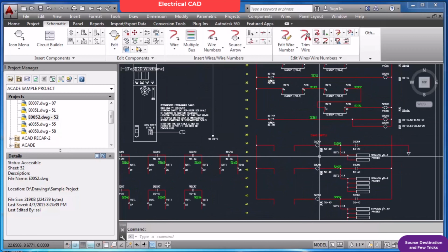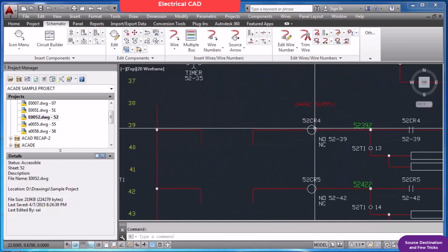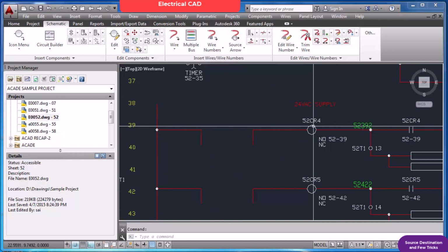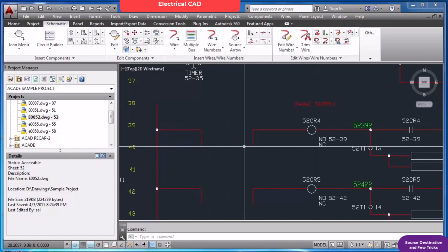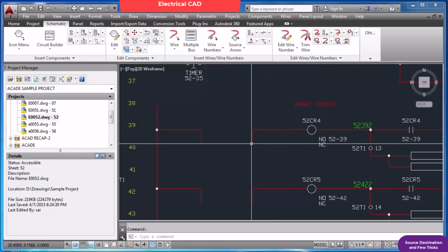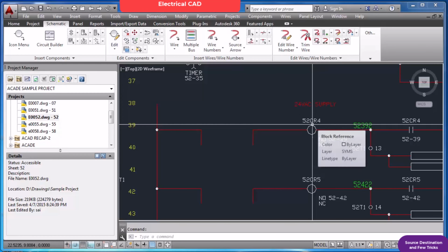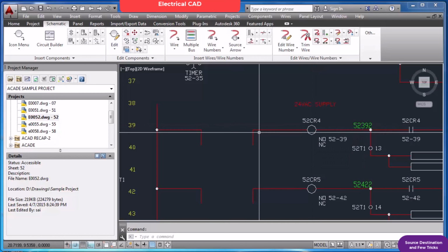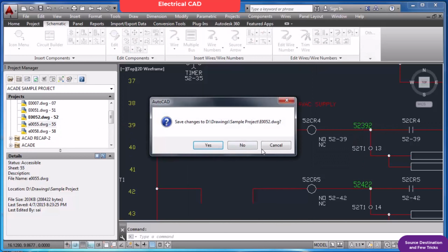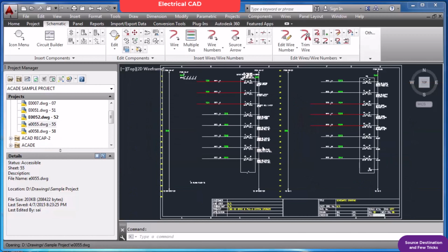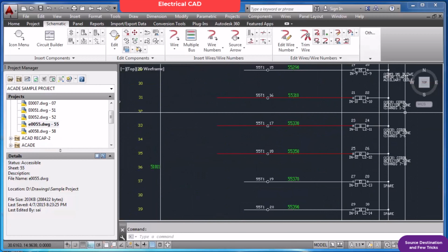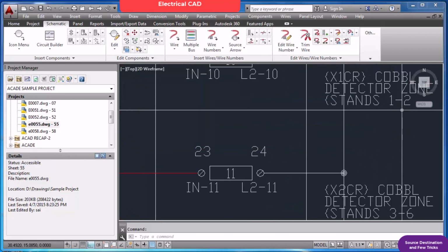And the same way, what we have to do is we have to provide a feedback. Once this is on, we have to give a feedback to the PLC also, that is input. That should go to the input card, saying that yes, this is on. So we should give one NO contact of CR4 to here. This is strand 1 to 2.